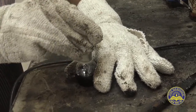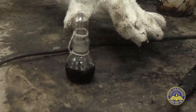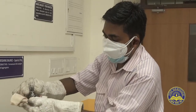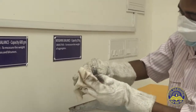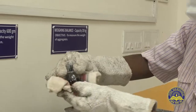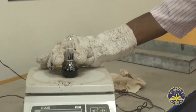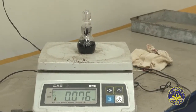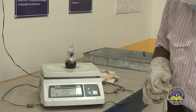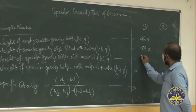Now I am putting the lid on the bottle. It has become very hot because there is hot bitumen inside the bottle, so I have cleaned the air bubbles off the outside of the bottle, and now I am going to take the weight of the bituminous material with the specific gravity bottle. Now the weight is 76 gram, because I am taking 50% of the material.